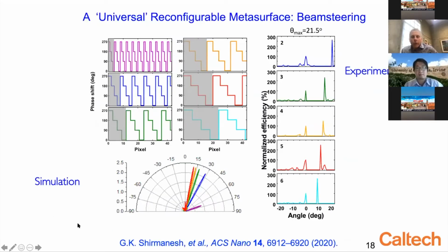So this illustrates, if we were to apply a 4-level phase scheme here between 0, 90, 180, and 270 degrees relative to some reference phase, a linear phase gradient where I gang together and apply similar voltages to an array of adjacent elements so as to approximate, using this electrically activated array of antennas, a linear phase gradient.